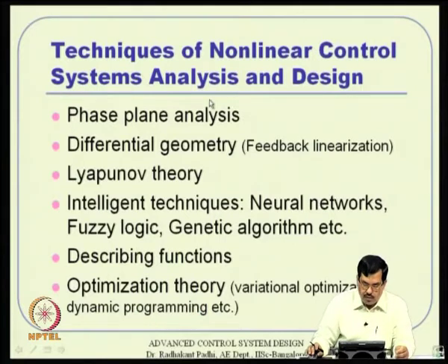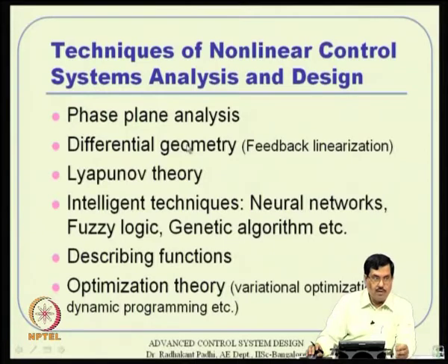When you talk about nonlinear systems analysis and design, there are a variety of ways that you can do that. There are a lot of techniques. First is phase plane analysis. This is valid for small systems like second order systems. It can be extended, mostly up to third order, but beyond that graphical interpretation is difficult, and hence we do not use that. And then there are differential geometry based concepts. Some of that we have seen already, that is feedback linearization or the dynamic inversion concept. Then Lyapunov theory, that is what we are going to see in this class and next class.